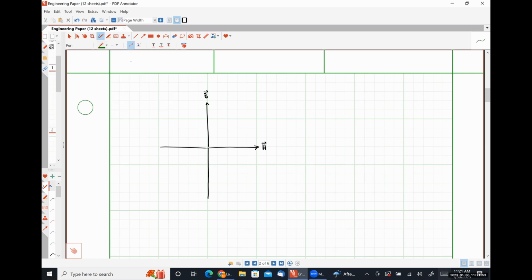And we are going to see something like this, okay? So for small values of H, the B field will be, if I could draw a straight line here to save my life, roughly linear, right? But as our H field continues to increase, we'll have this knee region until we reach a saturation point, okay? So this section of the curve here, 1, corresponds to the initial magnetization of our material.